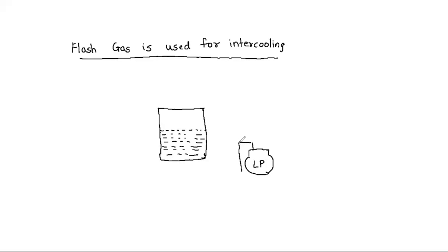Let us say that the gas is entering from the evaporator, the refrigerant gas which is evaporated. From the evaporator, the refrigerant would enter the low pressure compressor. And let us say that the discharge from the LP we bubble into the flash chamber.